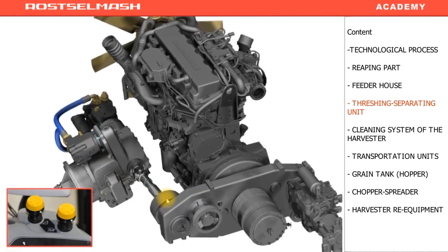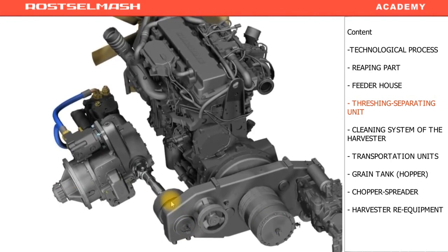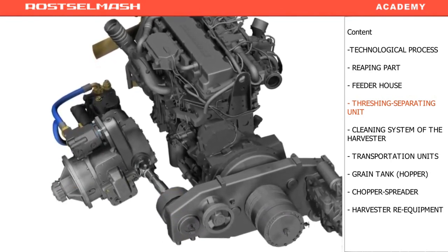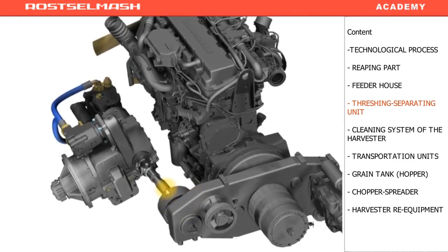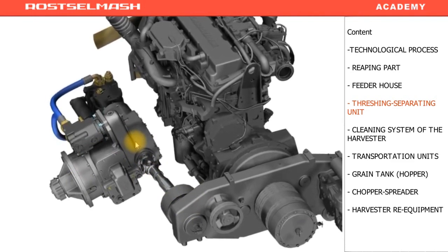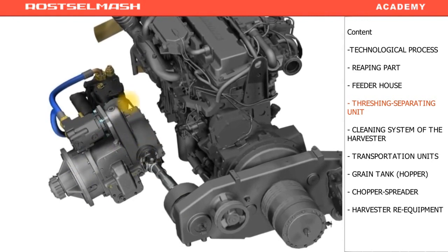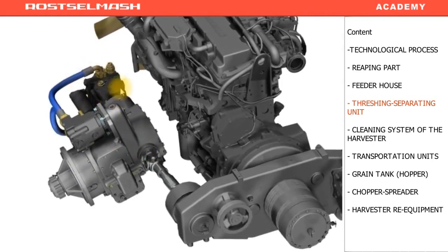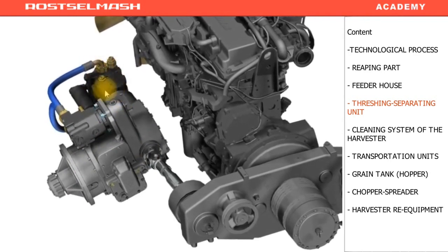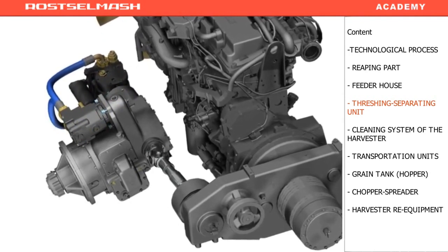The friction couplings are located there. Due to oil pressure, these friction couplings are squeezed, and the torque from the reduction gear goes to the driveline, and the reduction gear starts rotating. On the reduction gear shaft, a pump of the hydrostatic transmission drive is attached. The pump of the rotor hydrostatic transmission drive and the rotor hydrostatic transmission motor are used to change the rotor RPM.